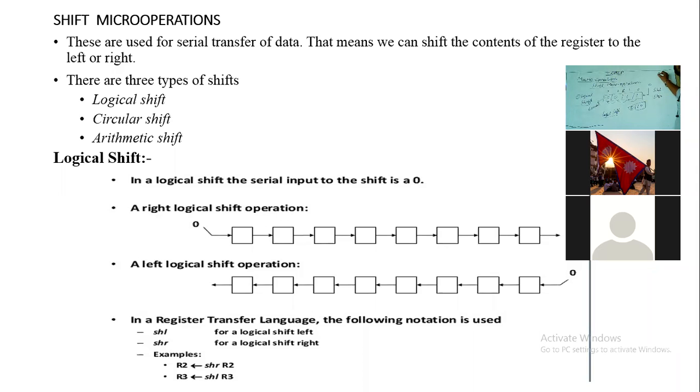If we have a register R and we want to perform logical shift on register R, how do we represent this? If you want to perform logical shift left, then you write SHL R. SHR R. Okay, what does it mean? This means shift the content of our register. In this operation, we logically shift the content of our register to the right by 1 bit.